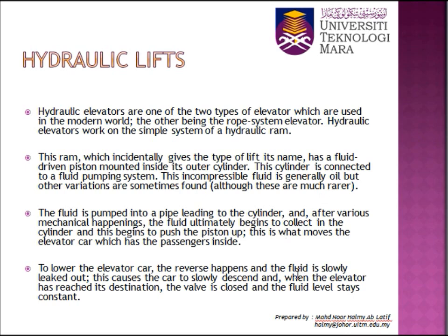So this is what moves the elevator car, which has the passengers inside. To lower the elevator car, the reverse happens and the fluid is slowly leaked out. This causes the car to slowly descend, and when the elevator has reaches its destination, the valve is closed and the fluid level stays constant. Okay, so this is how it works.